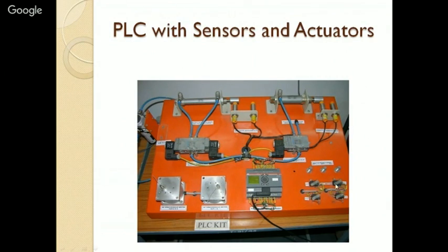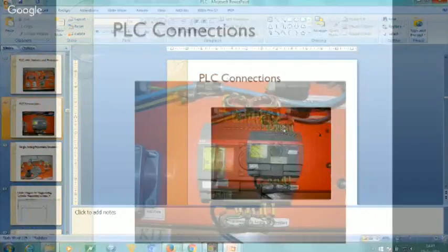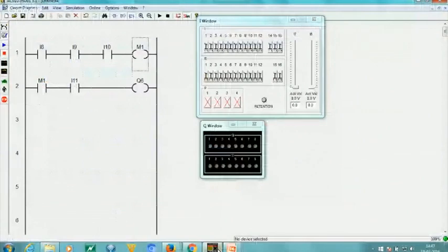And the last 4, they are limit switches, so they are contact type. The first 7 are proximity, the last 4 are contact type. Now in our PLC, out of the 12 inputs, 2 inputs are provided where analog sensors can be attached. They are input number 7 and 8. Now let us go to the simulator to understand 7 and 8.